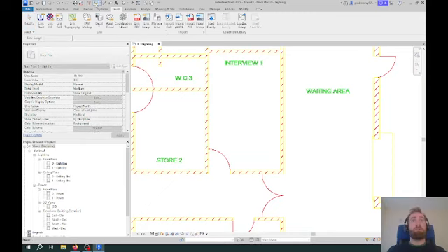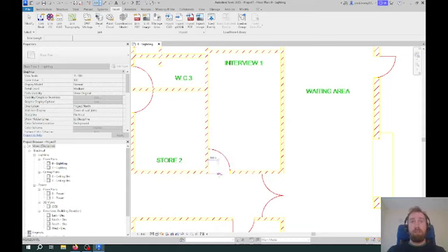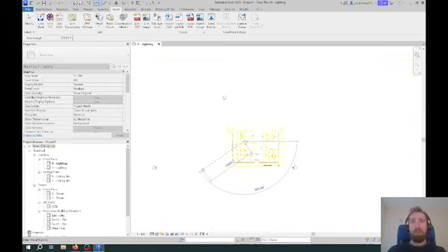One way to check is to measure a known element. For example, if I take the measure option and go across here, it's saying that a single door is currently 381. And with Revit, if we type in UN, it'll show us the units that we're actually referring to in Revit. So length is measured in millimeters. So we know now that currently it's interpreting that drawing as the door being 381 millimeters wide, when we know that's not correct. That's not wide enough. The standard door would be typically 900 millimeters wide. So there's an issue there. That drawing has been imported incorrectly.